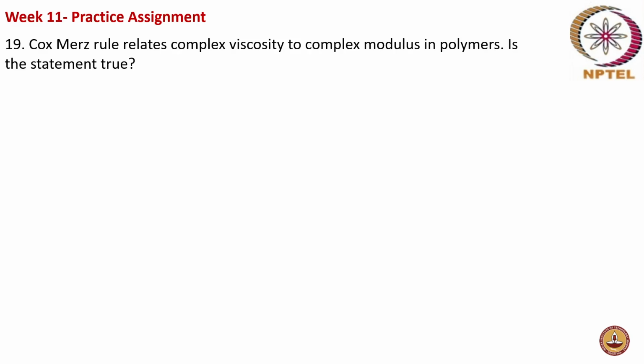Now, next. Cox-Merz rule relates complex viscosity to complex modulus. Sorry, there is a typo. It's not complex viscosity to complex modulus, but it's complex viscosity to your steady shear viscosity in polymers. Sorry. Cox-Merz rule relates complex viscosity to complex modulus in polymers.